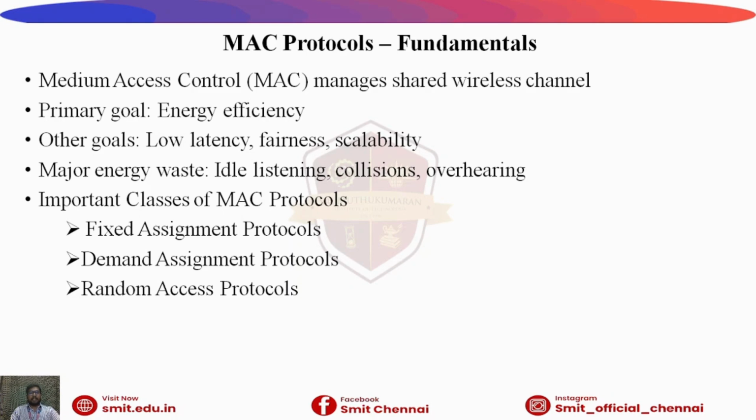Major sources of energy wastage include idle listening, in which the node stays awake without receiving any data. Collisions, where retransmission consumes energy. Overhearing, which means receiving packets meant for others. Thus, MAC protocols aim to minimize these losses.